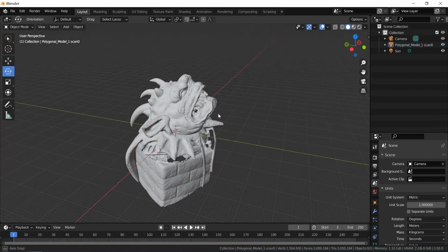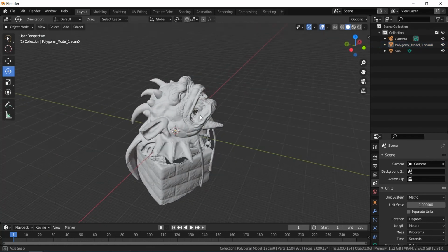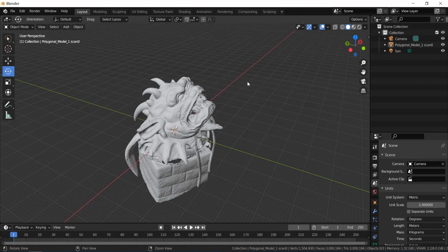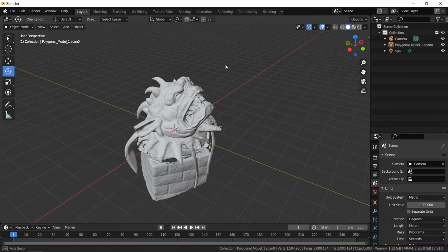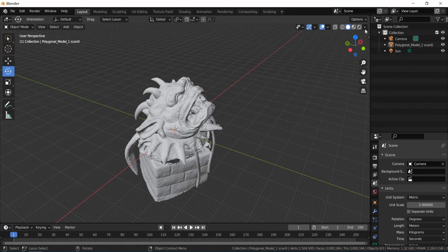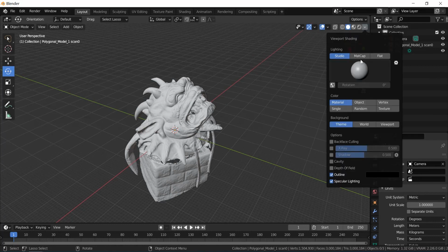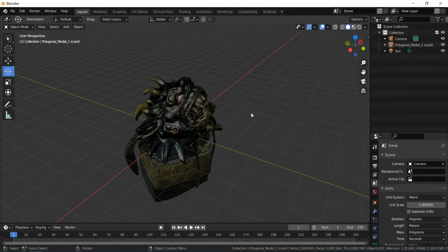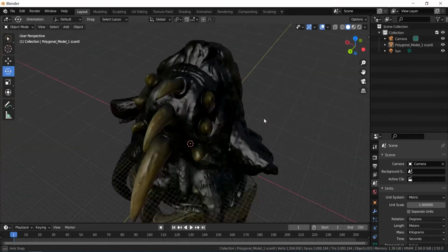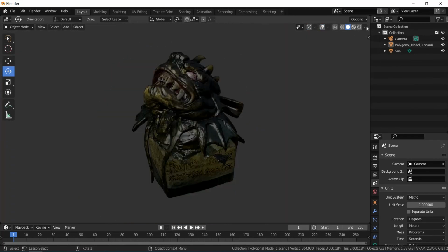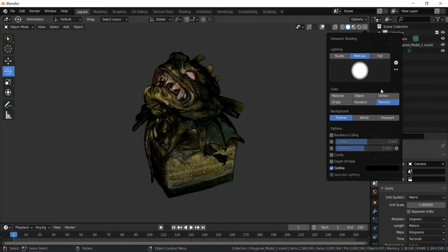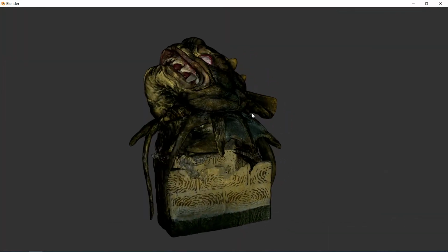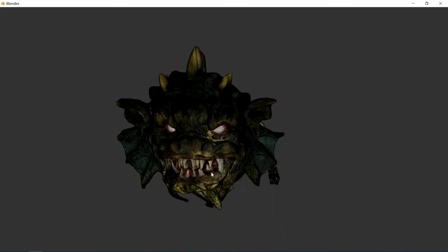We can find that the current OBJ file has no texture. Could it be that our OBJ textures were not imported together? No, this is because Blender hides textures by default. We only need to uncover the texture display. Click here on the small drop-down arrow. Select Color Texture. Look, the texture is displayed, but it doesn't look pretty. Don't worry. We select a matcap that is not affected by the light very much, so that we can have a better observation of the texture. Have you got it? Just try it according to what I taught you.